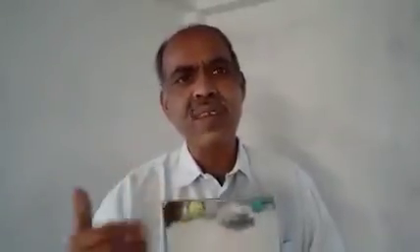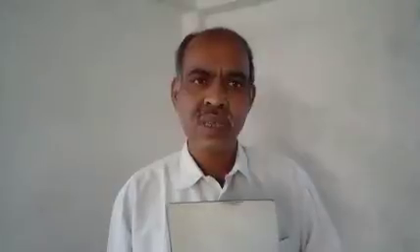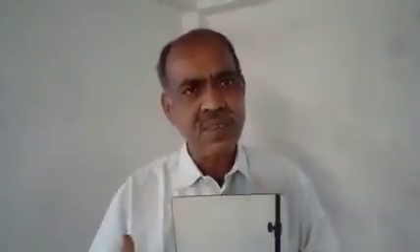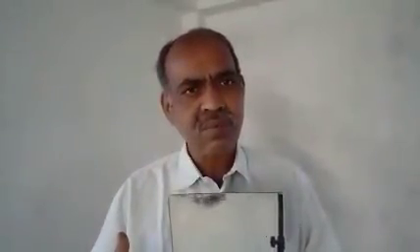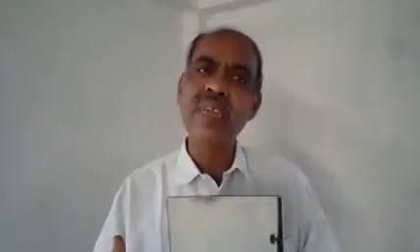Two forces are there, reaction RA and reaction RB at the two ends. Then RA plus RB is equal to 150 G. You can again calculate the weight this way also. What is this length? It is L. What was the intensity of the load? It was 300 G by L.